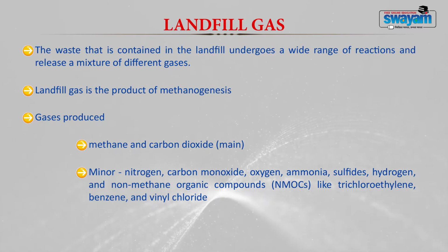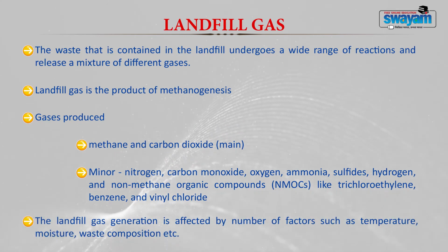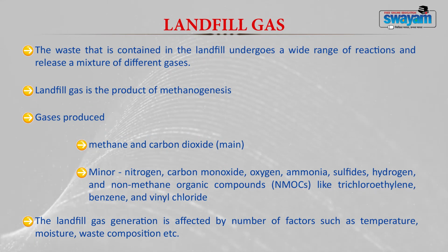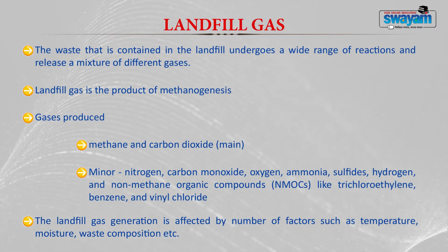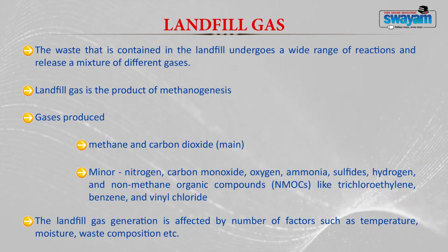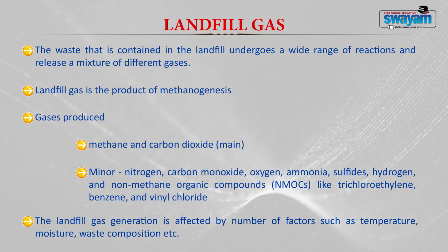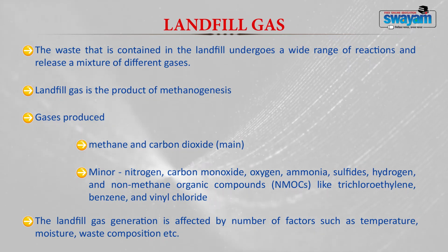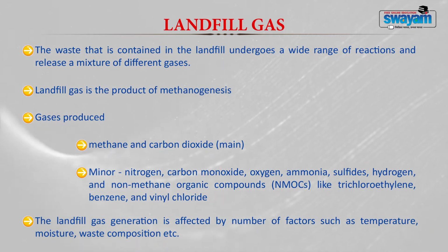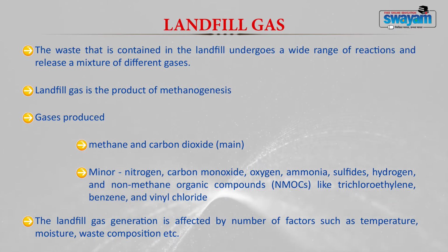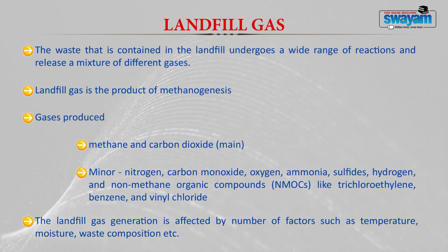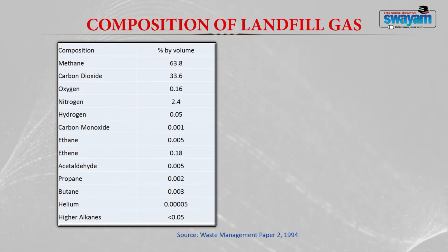The landfill gas that is generated is affected by a lot of factors like temperature, moisture, waste composition, etc. Now, the higher the temperature, the more gas production, because there is more biological decomposition of the waste. Appropriate moisture should be there. If moisture is less, then waste degradation will be delayed and gas generation will also be less. Likewise, for waste composition, if a greater amount of biodegradable material is present, then gas generation will also be high. Now, this table gives you the composition of landfill gas.